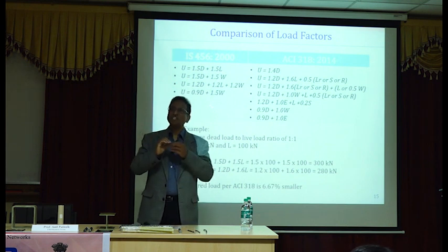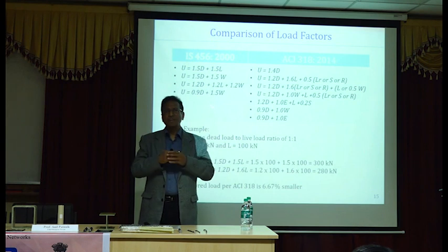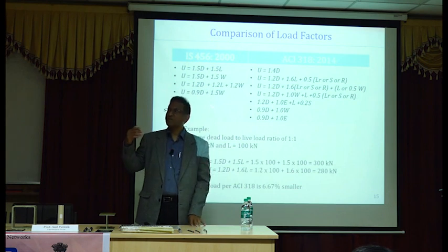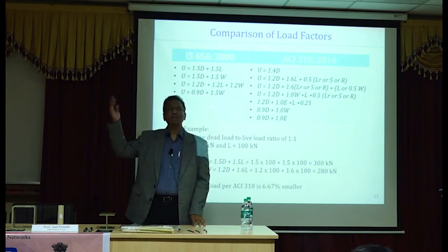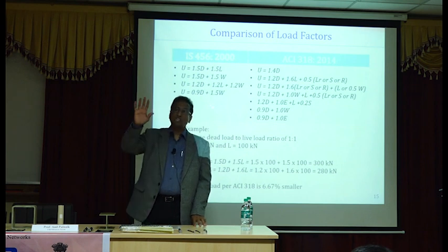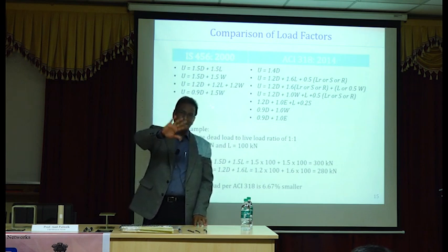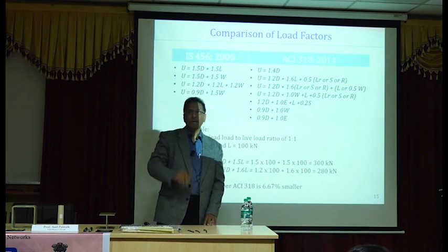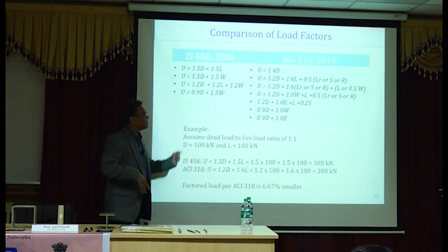It can have very large cracking, very large deflections. You may have to tear down the structure and build it again, but the structure itself should not fall over or collapse. That's the whole point of earthquake resistant design. But anyway, we are deviating from our discussion.